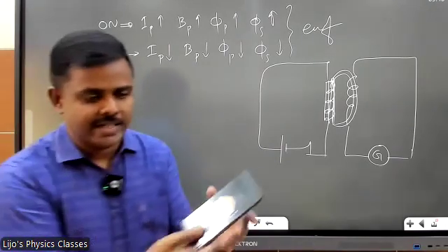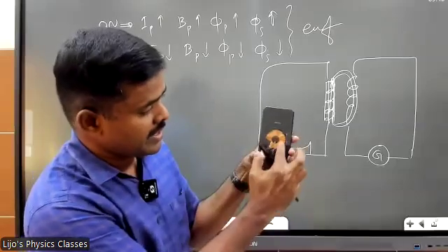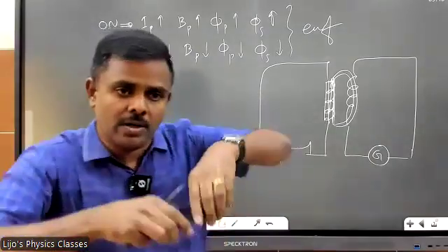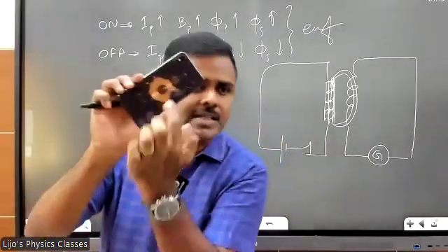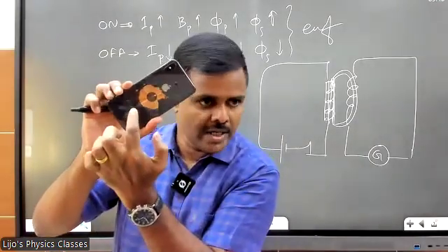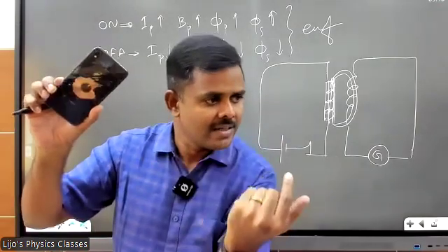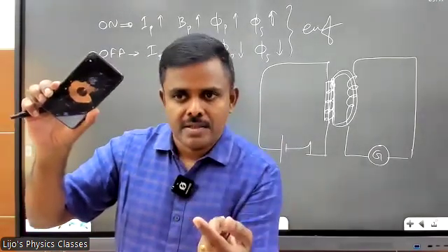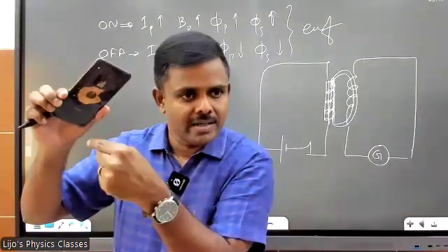That's it. This is the secondary coil. Look at this. That is a coil, secondary coil, okay? Right. So this is the secondary coil, and you're putting it on top of a charging pad. And inside the charging pad, there is another coil similar to this. That will be the primary coil, and the primary coil will have a changing current. So changing field, so changing flux, which will induce a changing flux here, which will charge the battery.